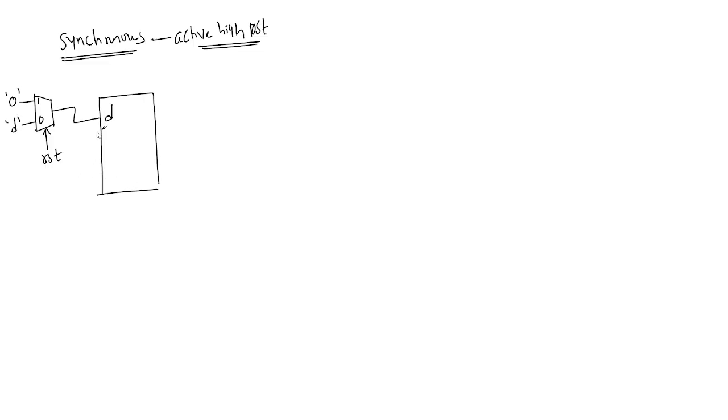Okay, so one more disadvantage of this synchronous reset means, in the timing analysis, you need to calculate the extra path for this mux also. Okay, so this is anyway clock is there. This is D flip flop, you have Q and Q bar. So this is synchronous active high reset. If it is synchronous active low reset, it will just change the inputs and outputs. Okay, so coming to asynchronous,